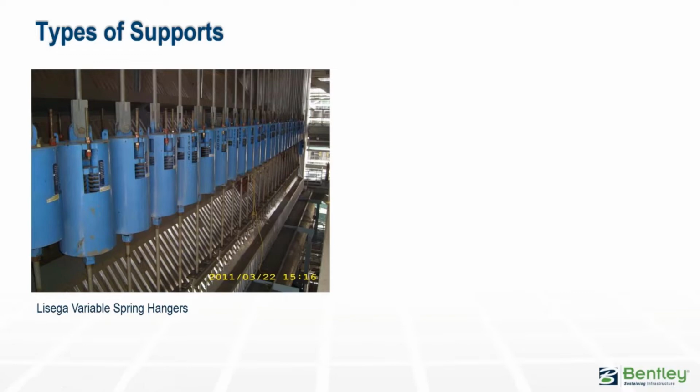This is basically a simple coiled spring where the load increases as the amount of displacement increases. They're relatively inexpensive, but they are load varying, so this can be a drawback with large displacements. And there's various types of variable spring hangers, and they're all slightly different. So as an example, a type 21 is a standard spring with an upper connection for suspension. A type 29 is usually under the pipe with a proper can. And a type 79 usually uses a trapeze with twin springs.